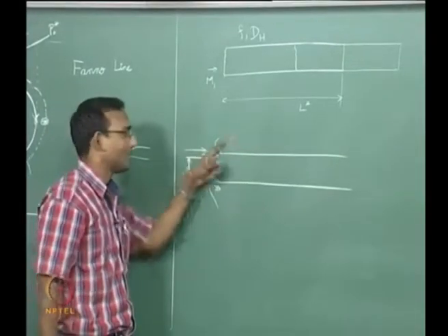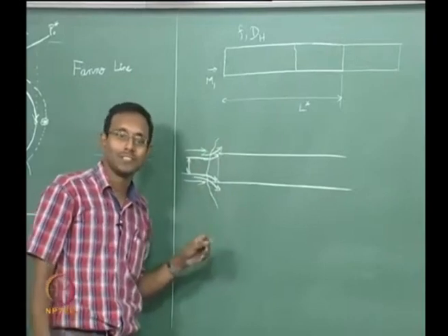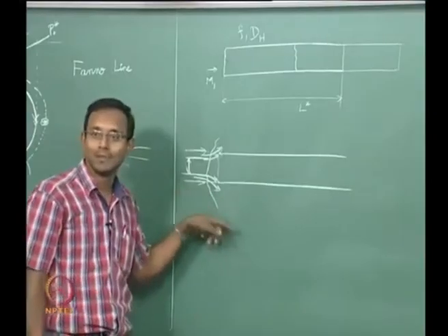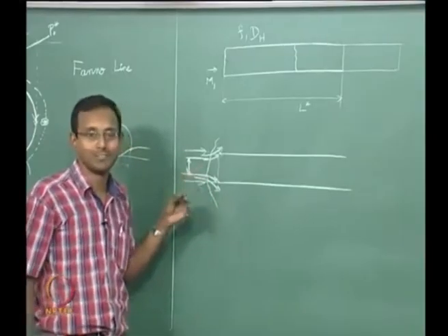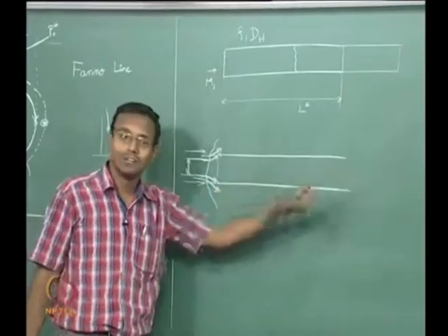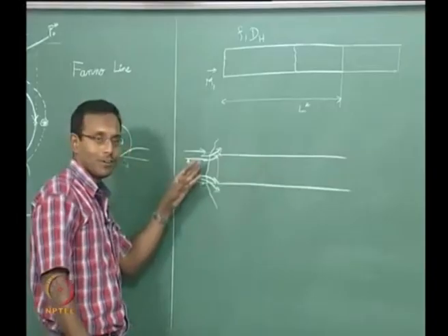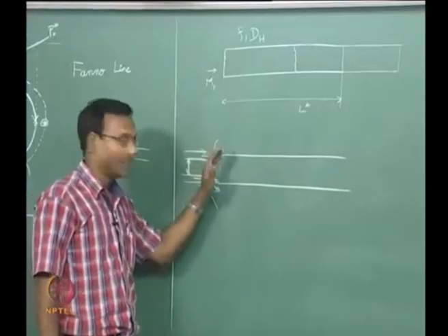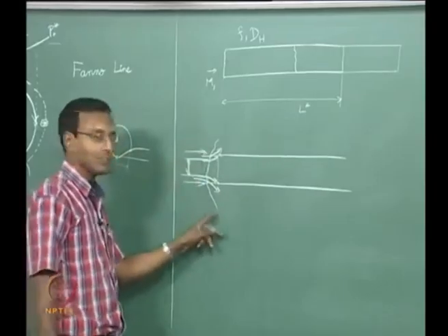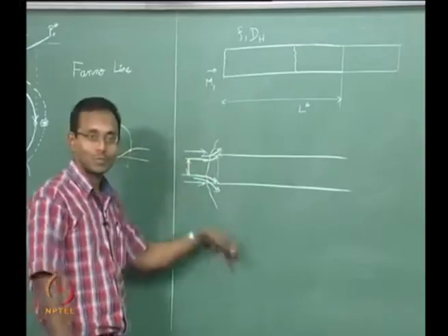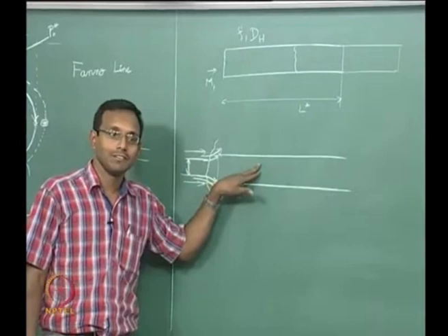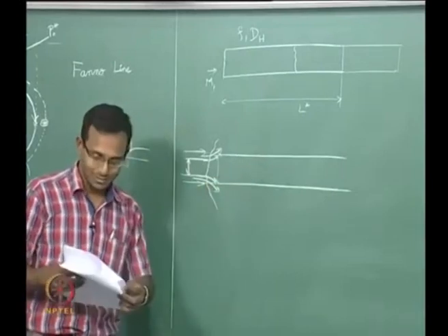This is called spillage. If you go to propulsion and study supersonic intakes, they will talk about spillage, and this is how spillage happens. This is one of the forms of spillage, of course. The shock comes out, and if I increase my length more, then there will be more compression waves coming out, making this shock even stronger. It will go sit more outside, which will make it more curved. So there will be more mass leaking out, more spillage, so that the net mass flow inside is even smaller. This is all just physical feel.